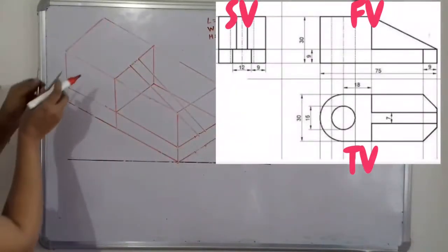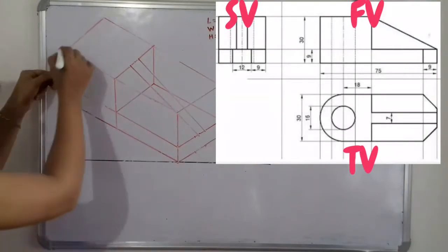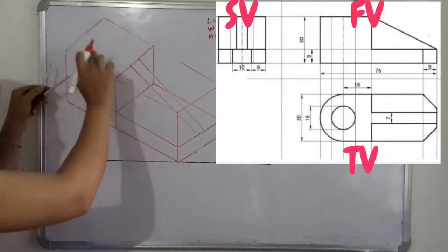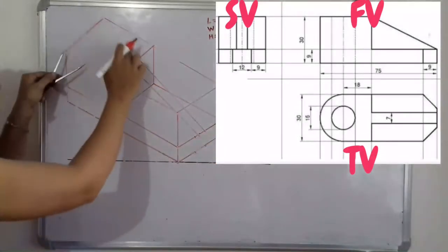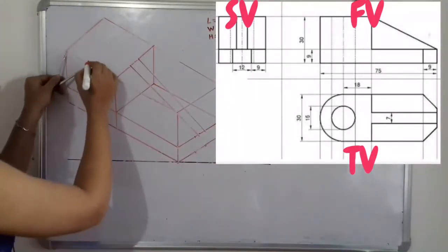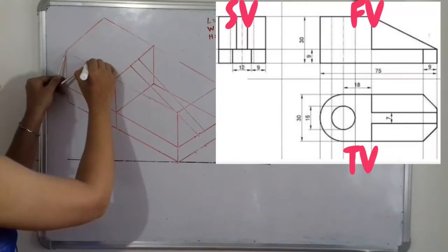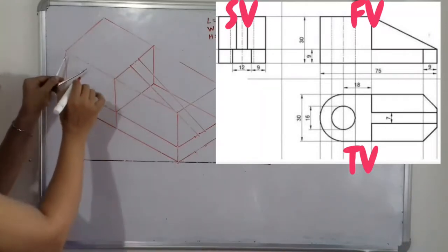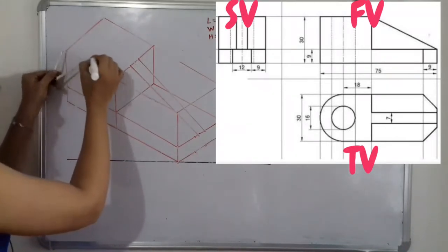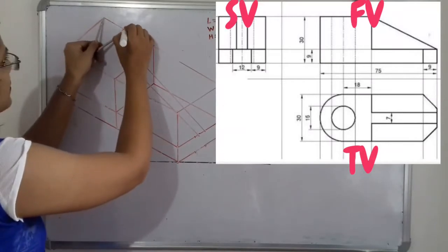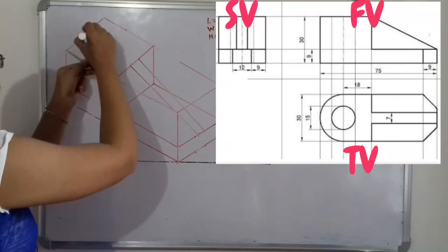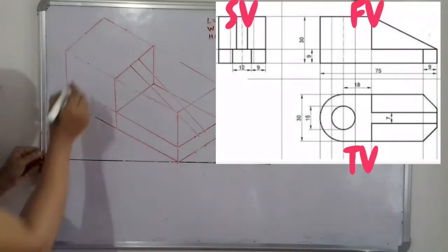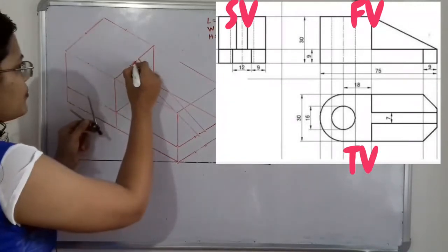So here we have how to select the center. On each line, remember that at this side there is the semicircular construction. So plot here the points at 60 millimeter, because here 15 into 4 is 60 millimeter. And also here at 60 millimeter, here is the middle point. Now from this point, here is also the middle point.